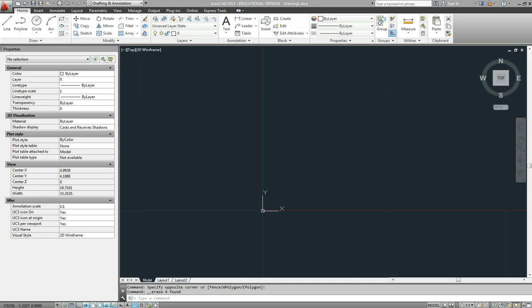So just starting our object snap exercise again, we will go into line drawing. We'll start with our starting point of 3, 3. To line drawing 3, 3, and across the bottom we're going to go relative distance of 4 in the X and 0.25 in the Y. Then we'll go vertically up by 3.